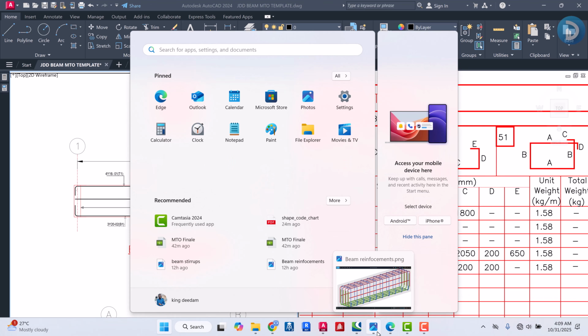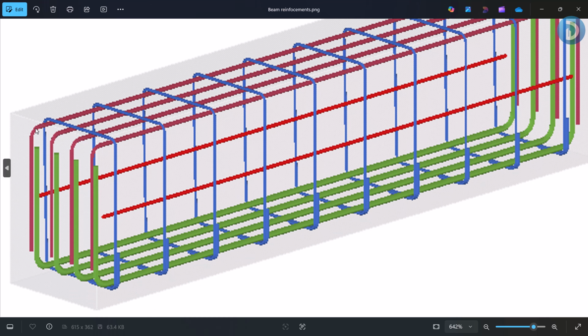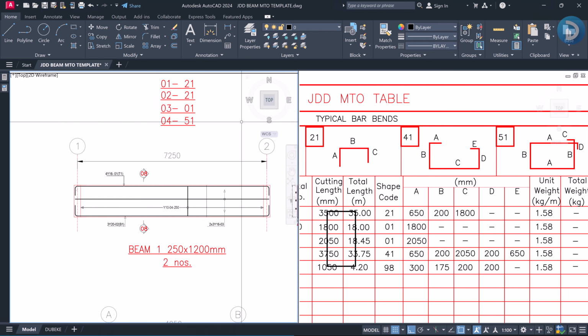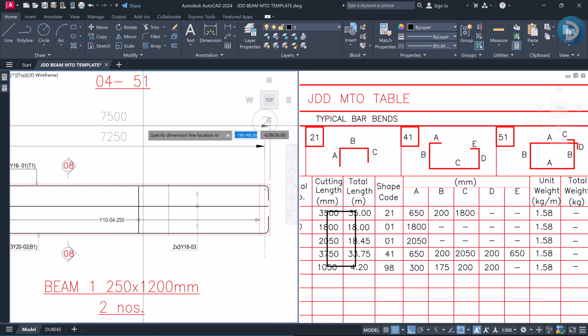So realistically, if we pull this up, we look at the length of our concrete beam, and we'll take out the concrete cover, because this reinforcement comes just after the concrete cover, right? For this respective beam, we are using a concrete cover of 40 millimeter. So if I dimension from edge to edge of this beam, because the distance we have here was at center to center,